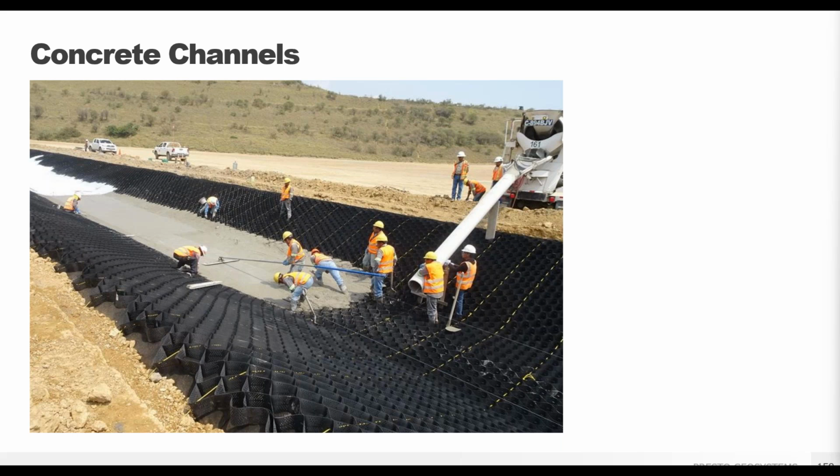If you have high flow or shear stresses for your channel armoring, you may likely be using a concrete infill for your GeoWeb channel, like this mine closure channel in Guatemala. Here we see the technique tip of filling the channel bottom first and then the side slopes. This is to ensure the system stays in place as no stakes are used, but can also facilitate construction as crews can traverse that channel bottom and finish the side slopes. Then for the side slopes, fill from crest to toe.